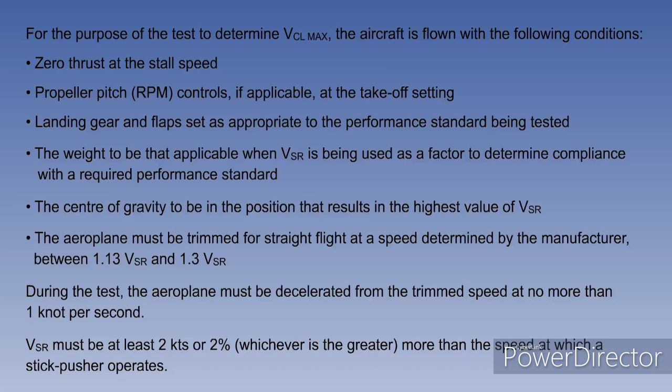VSR will vary with each of the conditions specified. Factors which affect VSR are thrust in excess of 0, wing contamination, and load factor. One thing that does not affect indicated stall speeds, however, is density altitude.